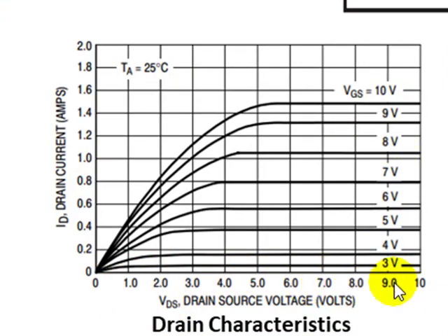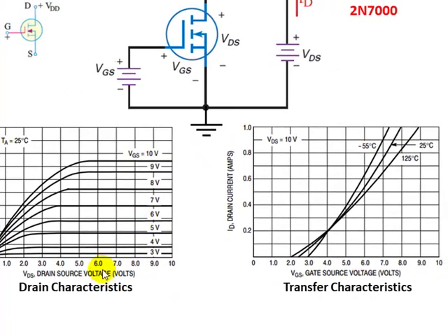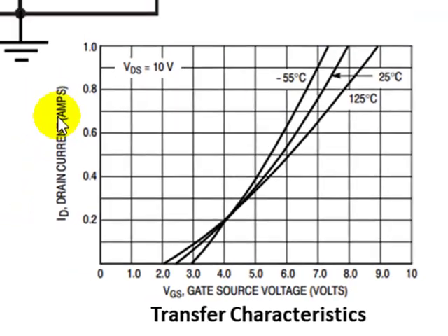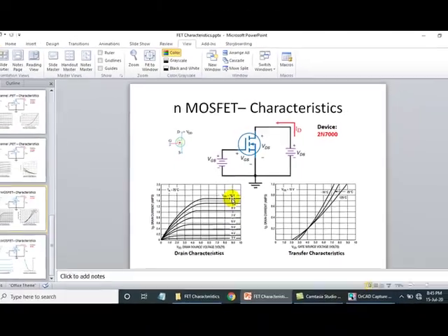And x-axis is VDS positive, y-axis is drain current, and VGS is also positive for drain characteristics. For transfer characteristics, primary variable is VGS, that is positive, and for different values of VDS you can obtain the transfer characteristic curve. I have already created the project.